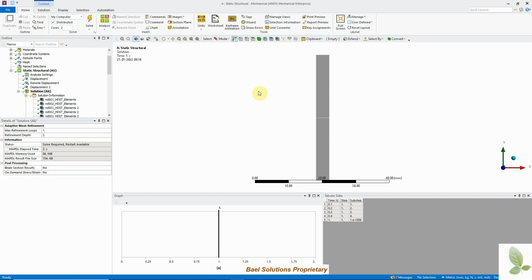We are now going to see a procedure for restarting a solution. For the solution restart, it is important to have restart points generated during the previous solution. Therefore, appropriate settings in the restart control before the first solution are necessary. We have seen in detail how we can specify restart controls so that we can generate the restart points at the required intervals. We are going to see this with an example.